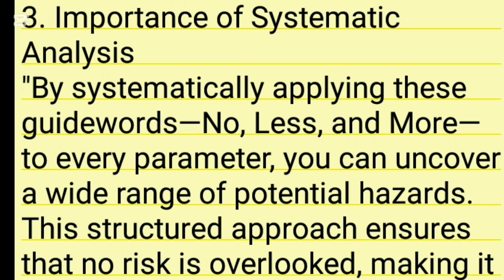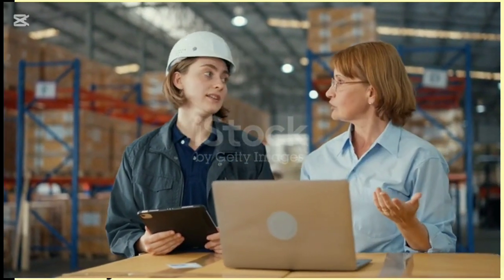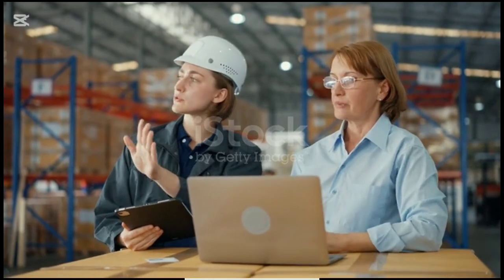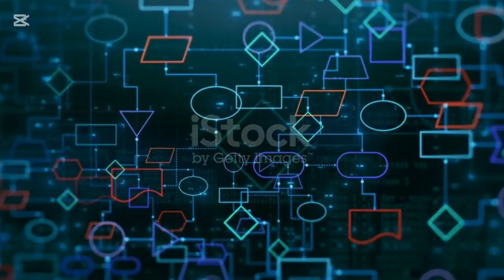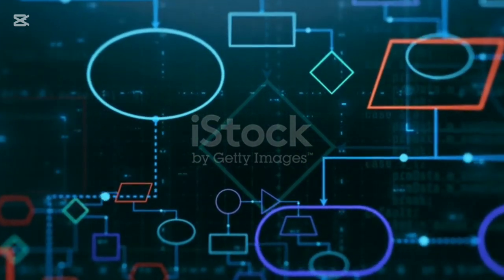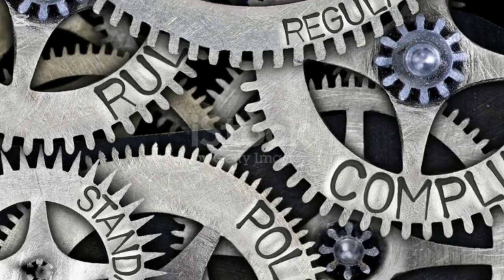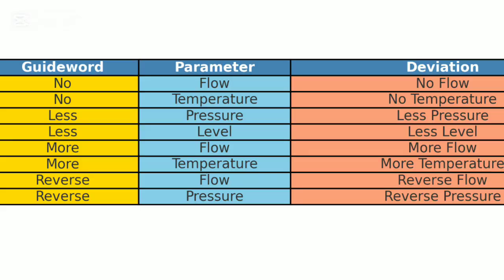Importance of systematic analysis. What is the importance of systematic analysis? By systematically applying these guide words, no, less and more, to every parameter, you can uncover a wide range of potential hazards. This structured approach ensures that no risk is overlooked, making it a cornerstone of effective HAZOP studies. Remember, the goal is not just to identify deviations but also to understand their causes, consequences and safeguards. This is why guide words are so powerful. They simplify a complex process.